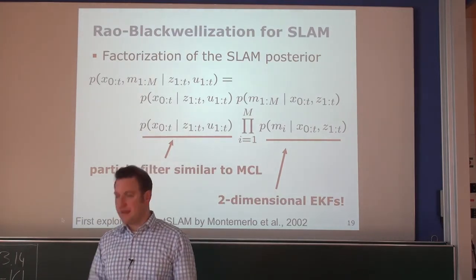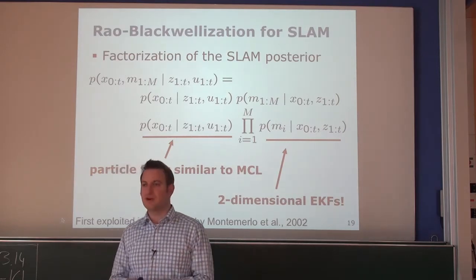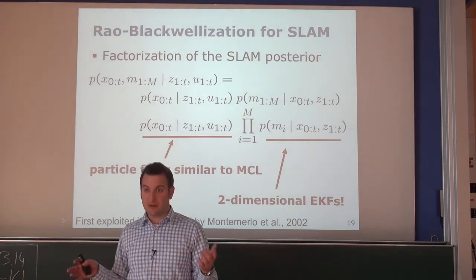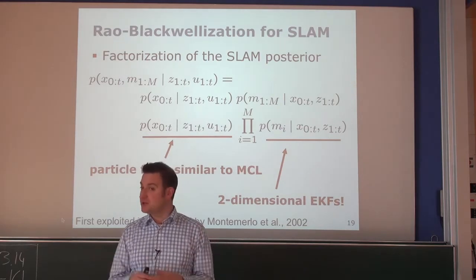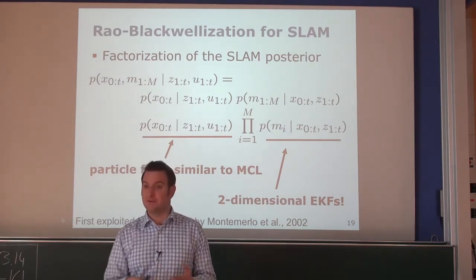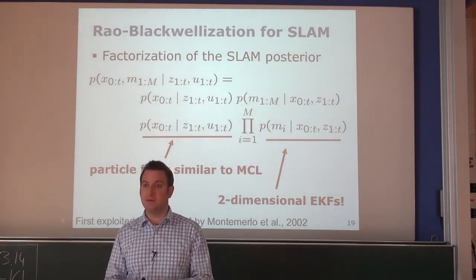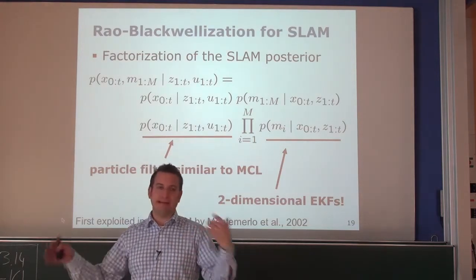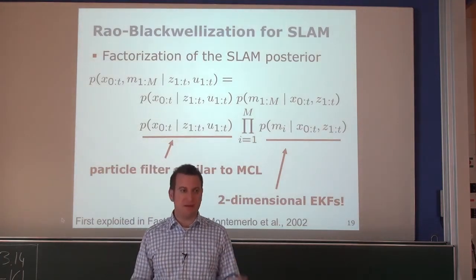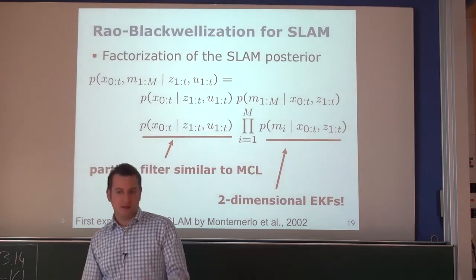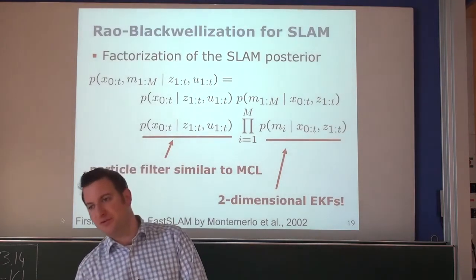If you have a different application where you directly want to start in a global reference frame, and you have an initial belief, you can distribute the samples according to this initial belief. That's basically up to you. In the standard particle filter, we say, I don't have any external frame, I just want to estimate what the map looks like. Then all the particles start with the same pose, 0, 0, 0.